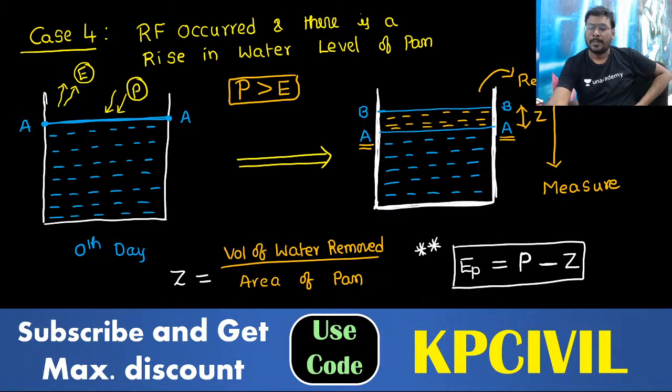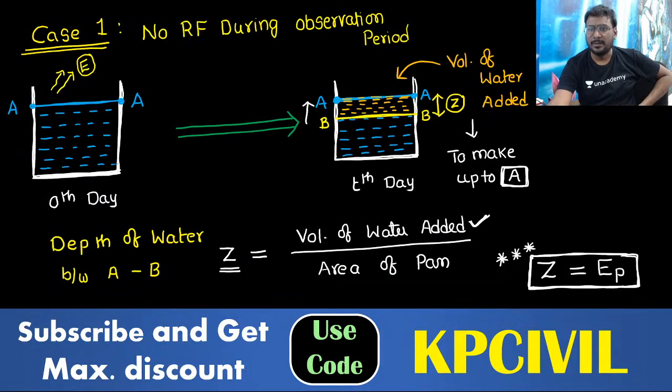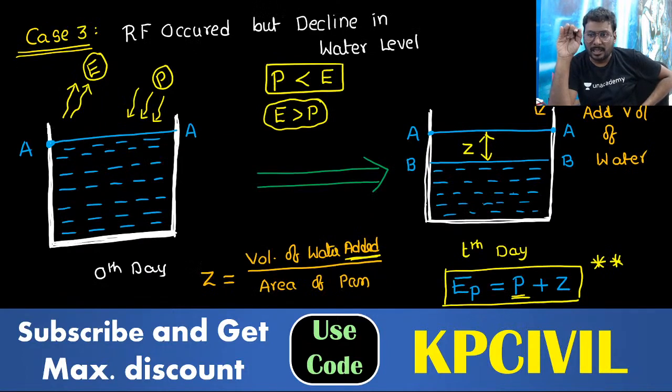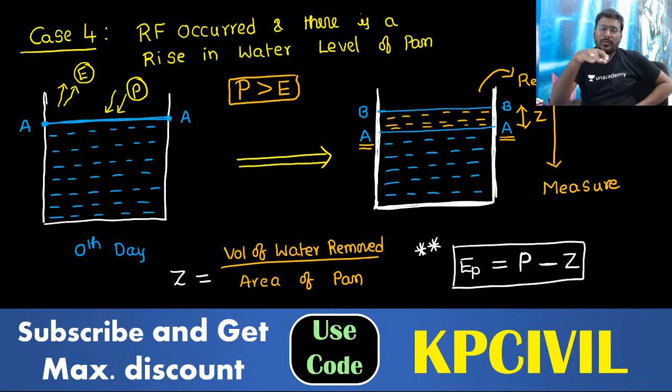4 cases. Case 1, rainfall not at all occurred, Z is equal to EP. Case 2, rainfall occurred but no change in water level, water level is constant, EP is equal to P. Case 3, rainfall occurred but there is a decline in water level, so EP is equal to P plus Z. Case 4, rainfall occurred, there is a rise in water level, EP is equal to P minus Z. 4 cases we are having related to evaporation measurement through pan.